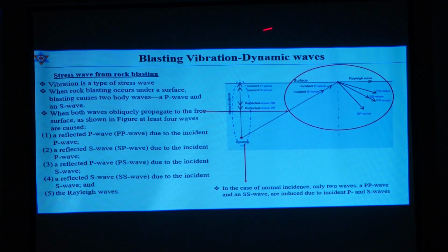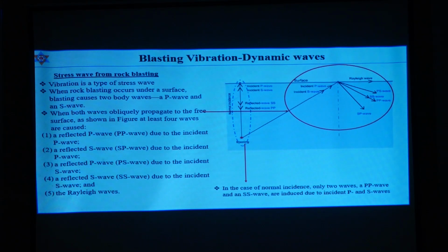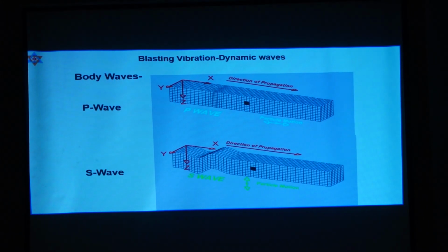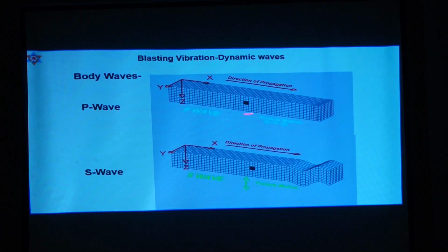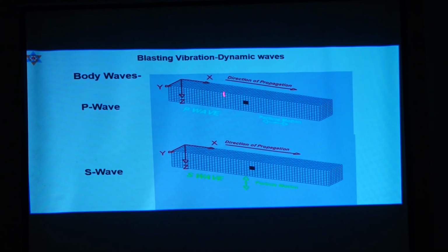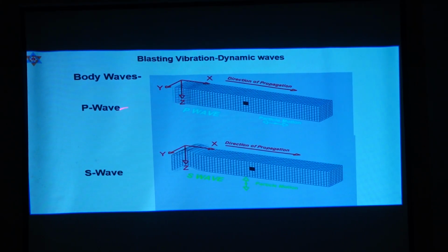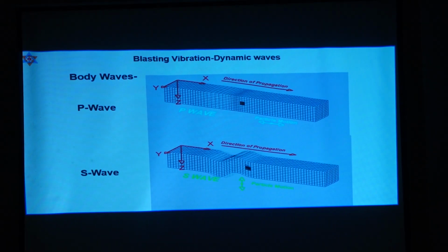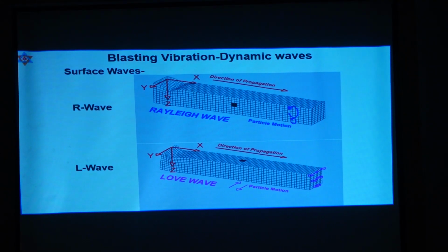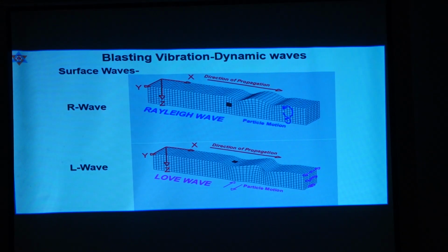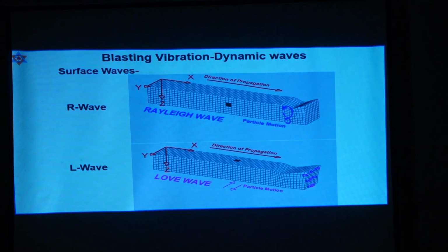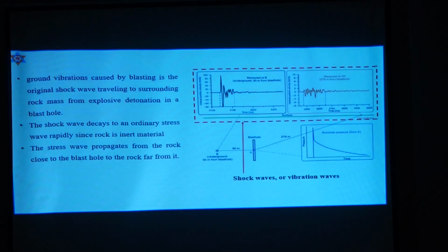If there is blasting, we have to measure over here, and how the propagation of seismic wave is, that is in the form of body waves, we know body waves, P waves and S waves, and surface waves. So here how the body waves move, and how the surrounding particles behave with the body wave, that is P wave and S wave, and thereafter surface wave, how these waves are propagated and the particle motion in relation with the surface waves.